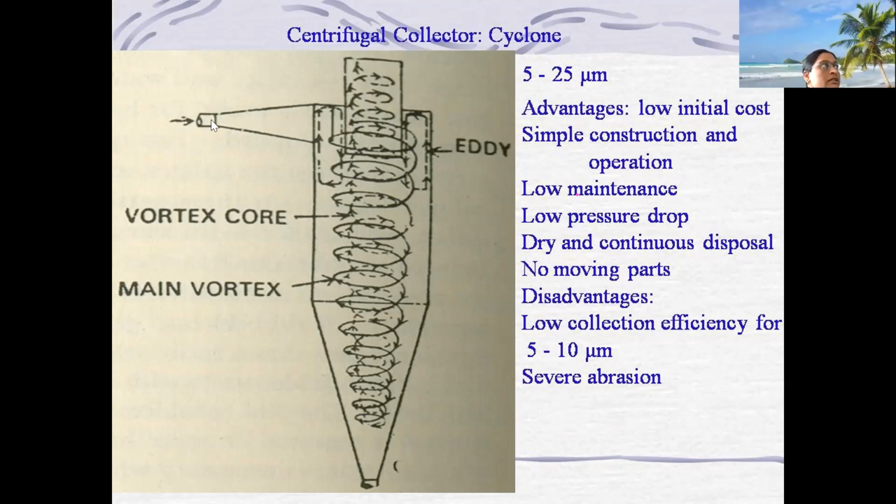The size of the inlet pipe is very small. The laden gas will be allowed to enter into this, and slowly the size of that inlet pipe is getting increased. Arrangements are made in such a way that the gas starts whirling. Automatically it starts rotating. We are giving vortex to this particular gas with this natural phenomenon. These are the natural, physical arrangements of this inlet chamber.